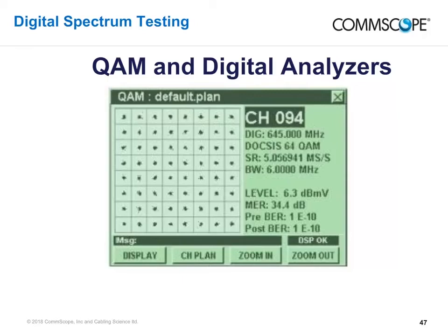Each of the stars, however, represents the instantaneous phase and amplitude of a modulated digital carrier. The fuzziness of the stars and the shape of the overall constellation provide information on signal parameters that can be used to troubleshoot and adjust system performance. Digital analyzers add qualitative information to the visual constellation display, such as bit error rates and noise levels. The specific types of information and their use in troubleshooting is beyond the scope of this primer, but you need to be aware that these aids are increasingly becoming a necessary part of your toolkit.